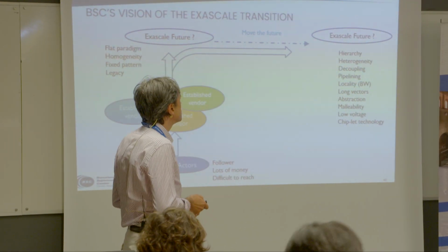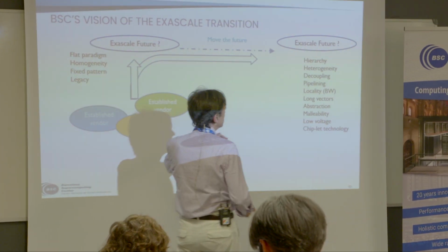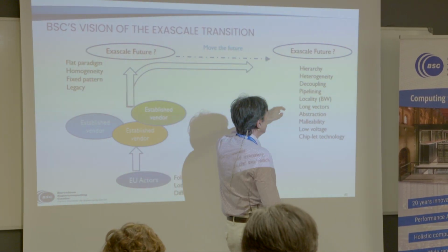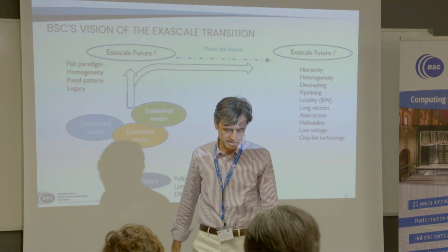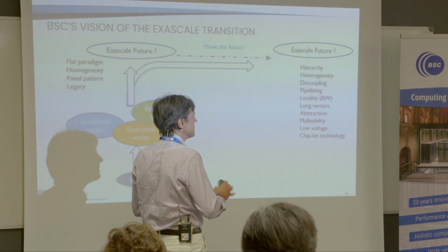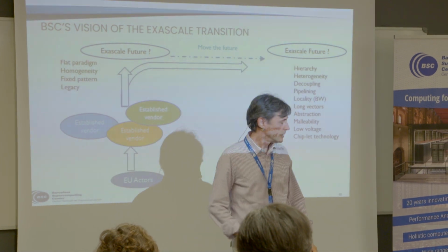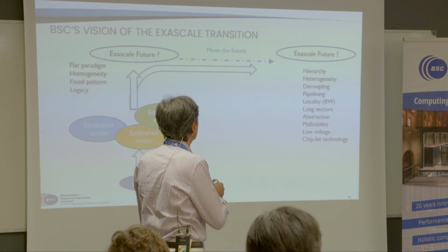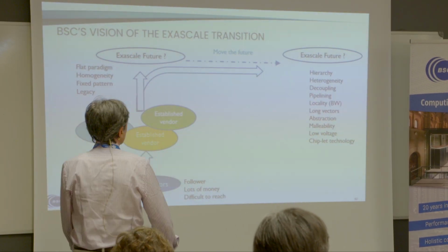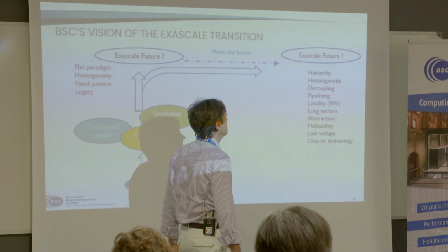So targeting a hierarchical parallelism and heterogeneous architecture, decoupled architectures, I'm going to talk about that, heavy pipelining, especially in the vector acceleration, and exploiting locality because the memory bandwidth is limited, and this is done especially through the use of long vectors, as we're going to see in a few slides. Abstracting the view of the architecture to the programmer,